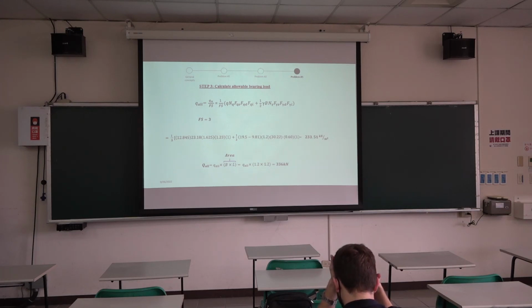One thing to note is that the difference with the water table cases is going to be mainly from this q, the surcharge, and also this gamma. Please note that the gamma we use in the last term of the bearing capacity equation is for the unit weight of the soil below the bottom of the foundation. That's something you should remember when you are doing your calculations.